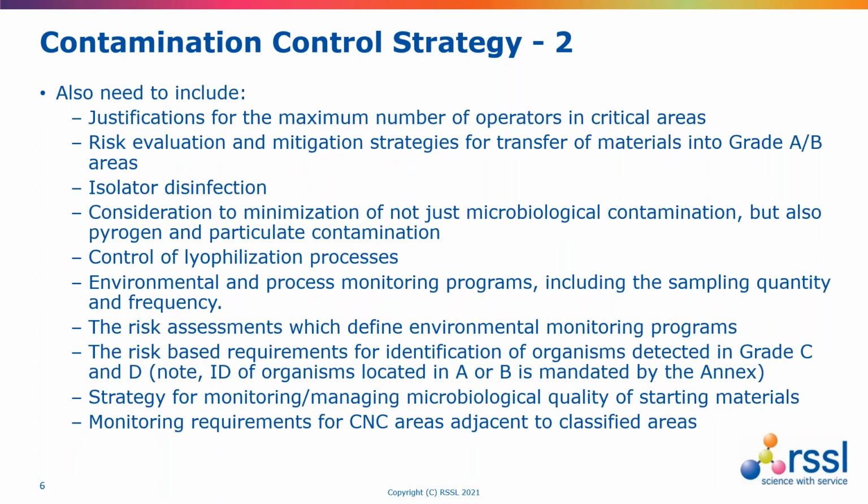But it's things like justifying the number of personnel who are permitted within critical areas, having a risk assessment and a mitigation strategy for the transfer of materials going into a grade A and B area, the process for isolator decontamination, aseptic processing controls and the risk criteria that come with those, consideration of minimising not just microbial contamination, but also, as I mentioned at the beginning, the risks around endotoxin and particles, because pharmaceutical parenteral products have to be free of visible particulates.